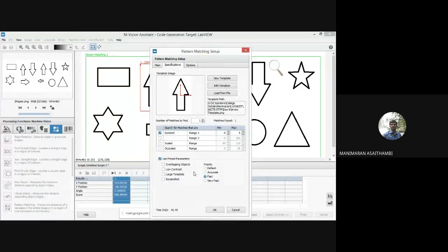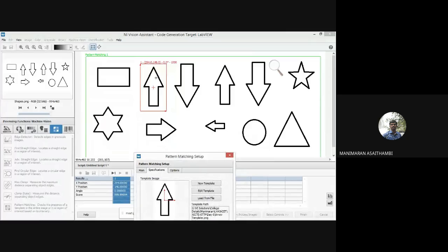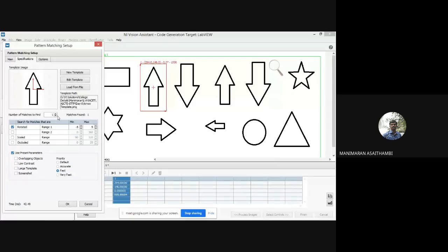Do you see how many matches I have got here? I have got only one match. This is the exact element. But I have one more arrow mark here. I have some arrow marks in this. So how do I define them? I'll say two matches. Exactly two things I have, because I copied this entire section into two. So there won't be any changes of alignment, distortions or size variations. So I can go for multiple matches. Say 10 matches I can find. So 1, 2, 3, 4, 5, 6 I can find, but it found only 2.